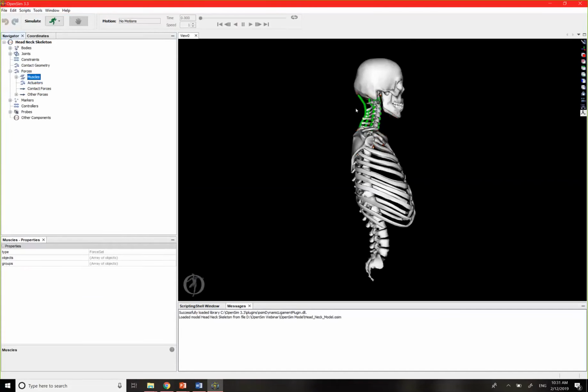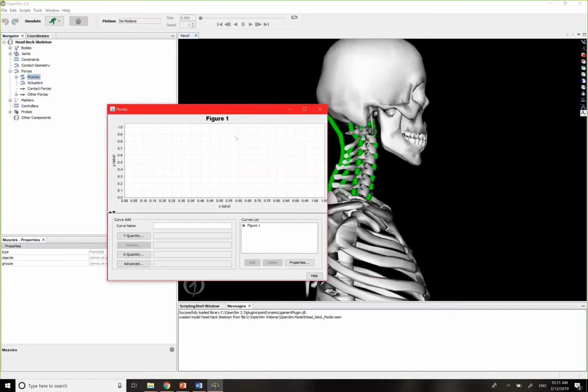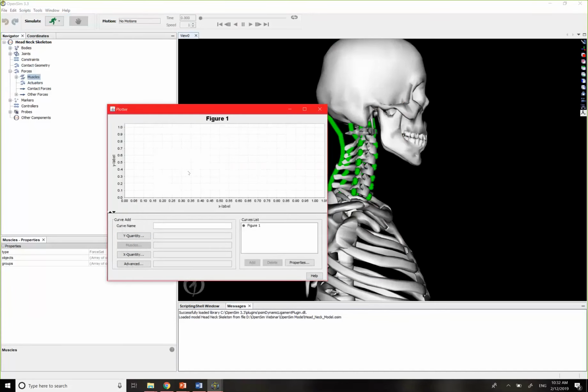And you should be able to see the ligament structure here, as we've noticed before. Now, if you run a forward dynamic simulation with this model, the ligament states aren't actually stored in the normal states file. What you want to do to pull out the states information from the ligaments is run the forward dynamics with a force reporter analysis tool, which reports forces that are produced by any force-producing structure inside the simulation. So I'm going to pull up an example of a force reporter file here.